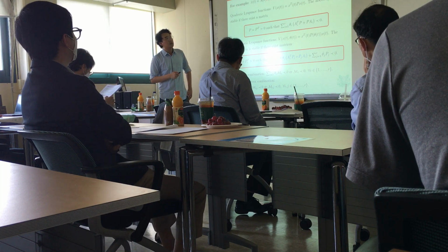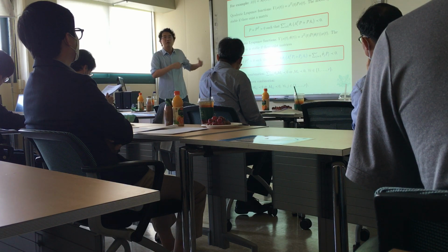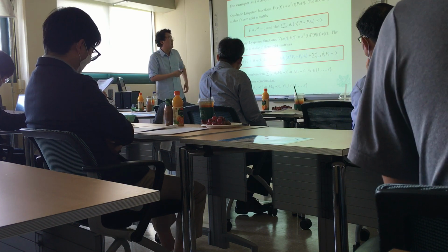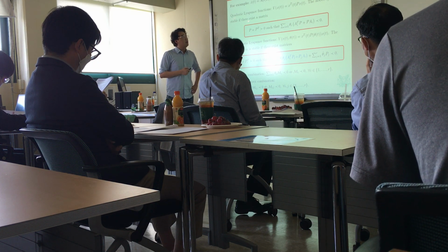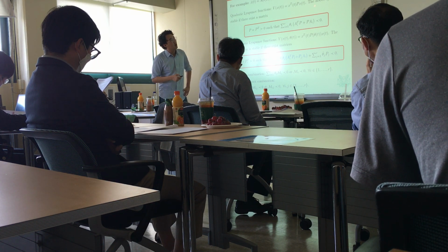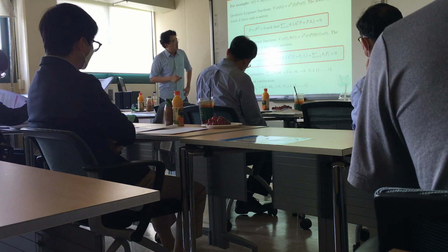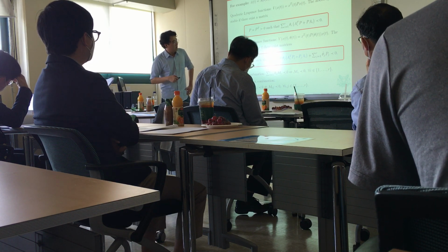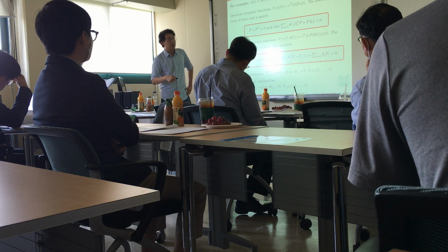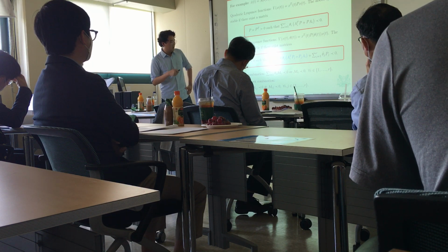That is the autonomous fuzzy model, where there is no control input and disturbance. With the help of the quadratic Lyapunov function, we can obtain the sufficient condition for stability of the system. If we use the non-quadratic Lyapunov function, we have this sufficient condition for stability of the system.